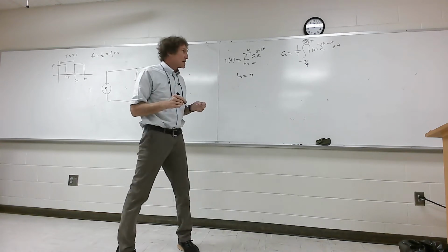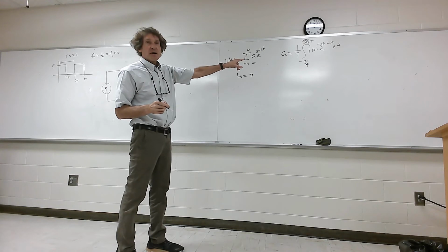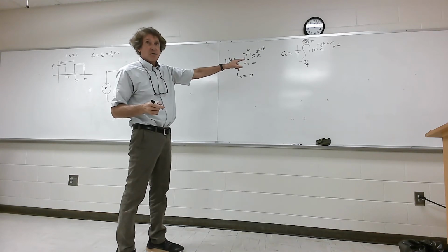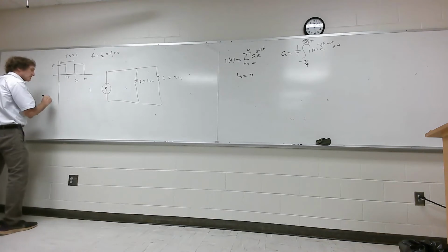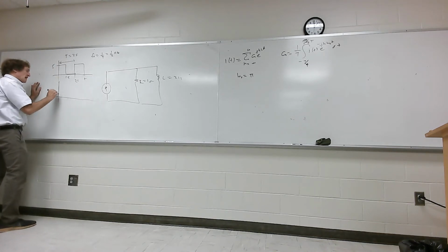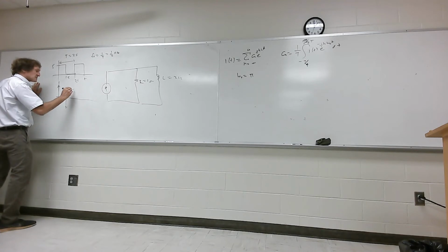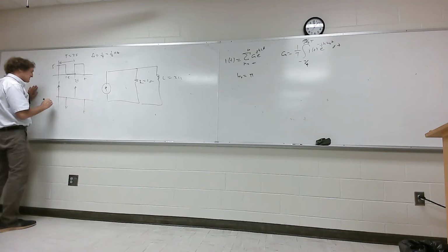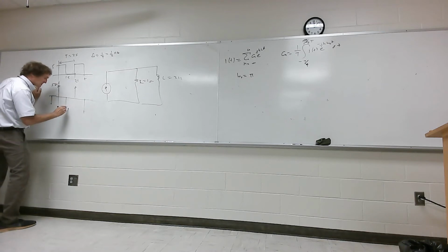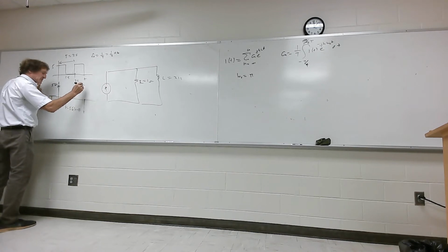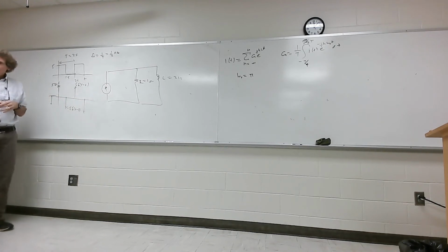Now the next thing I have to get is this value of c of n, but I'm not going to use that integration. That will work, and you can just integrate the function right there; it's not a bad one. But what I'm going to do is take a derivative. The first derivative is the thing I really urge you to remember. I get this, and this, and this, and it repeats itself. The value here is 5 delta of t, here it is minus 5 delta of t minus 1 second, this is 5 delta of t minus 2 seconds, and so forth. You all follow how I got that?